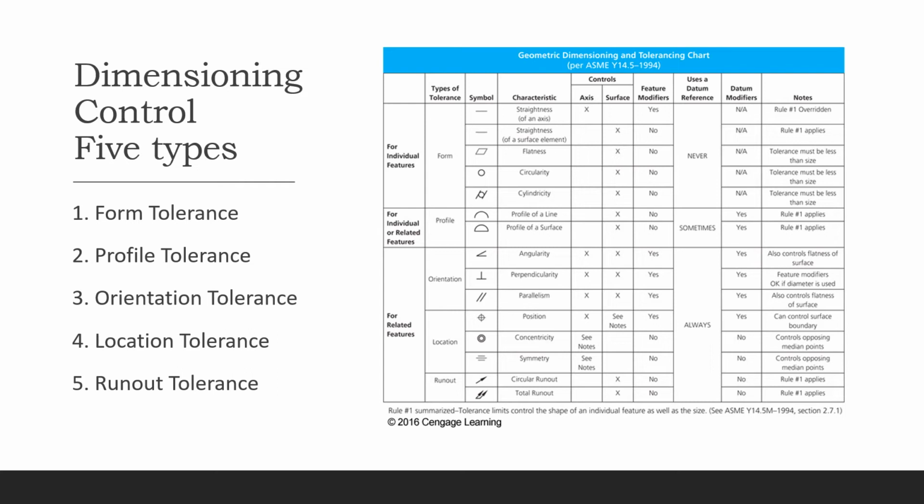Again, when we measure this one, what is my tolerance limit? You might be a little off or deviated from that shape, and that's my tolerance. So that would be parallelism, an orientation tolerance. You can see that more and more later.